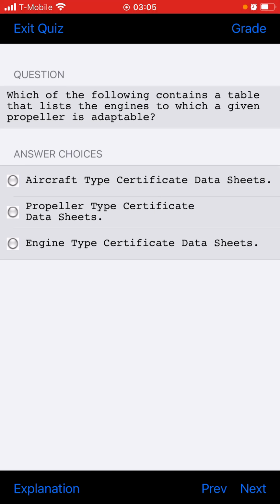Weak brush springs. Arcing at the brushes and burning of the commutator of a motor may be caused by weak brush springs.